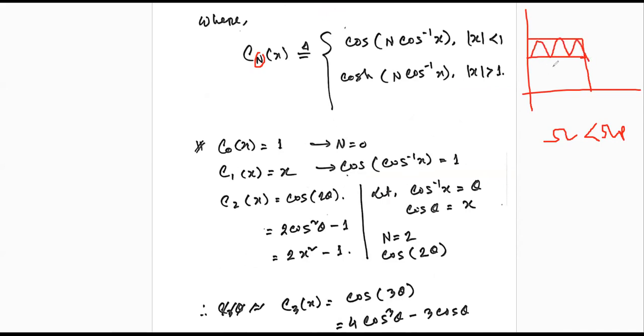So at this moment we use the cos function. We are not going to the cosh. When will we use cosh? Outside the pass band. So we are now taking this formula. Put n equals 0 there. What should be the value? If n equals 0, this will be cos 0. Cos 0 is equal to 1. Now put n equals 1. What will be the value?